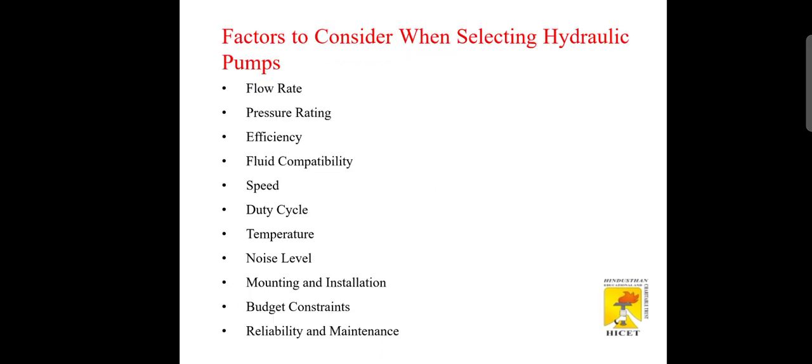Next I am going to explain the factors to be considered when selecting hydraulic pumps. Mostly, pumps convert low pressure fluid to high pressure fluid for various applications. So for that we have to consider flow rate, pressure rating, efficiency, fluid compatibility, speed of operation, duty cycle, temperature consideration, noise level of the fluid flow, mounting and installation of the system, budget constraints, reliability, maintenance and troubleshooting.